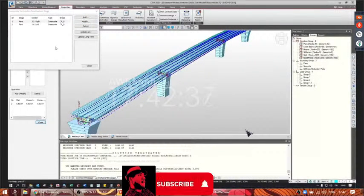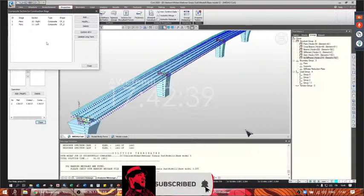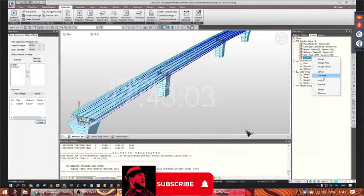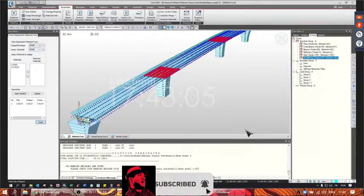Okay, so we apply the same for the left beam. Then the Eurocode 4 Part 2 provides that for continuous bridges, due to the negative moment on supports that cracks the tensile concrete, we have to not consider the stiffness of the slab for 15% of the span on each side of internal supports. Then we are going to assign a zero stiffness for these elements, like here.